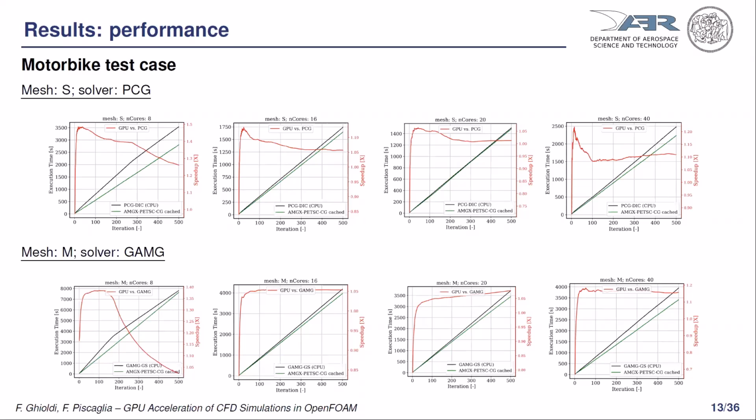Yeah, but again, we are talking about smaller meshes and a few number of cores. So in this case, this is just the fact that for a few number of cells, at the moment in the current state, because of the way GAMG is written in OpenFOAM, because of the efficiency that it has, the much larger improvement is found in, again, PCG against PCG.